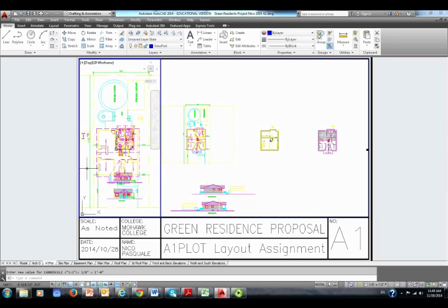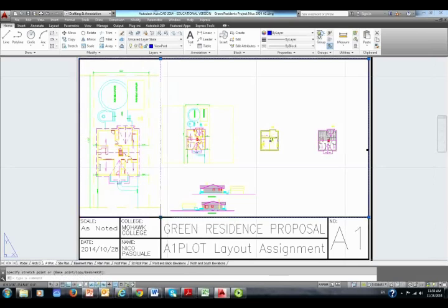I see that my site in 1/8 of an inch fits nicely with where Nico placed this vertical line. So the layout looks good. So I'm going to save this, go back to paper space, and select this viewport. What I need to do is now bring it in. Site plan is ready. A little bit of a title here, 1/8 of an inch scale, and site plan is ready.